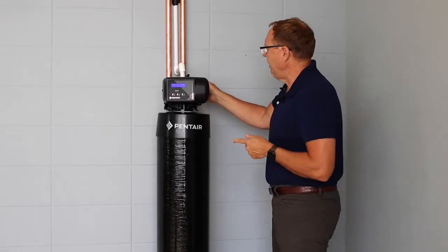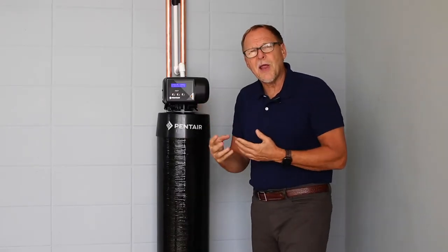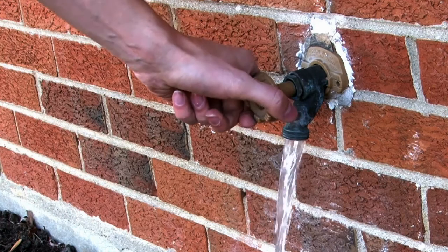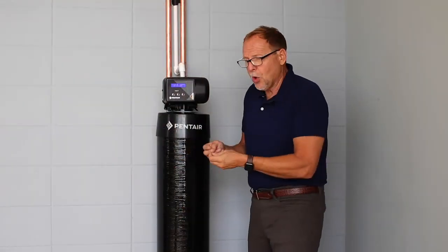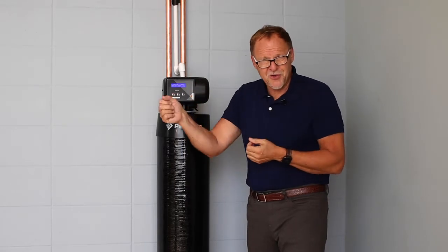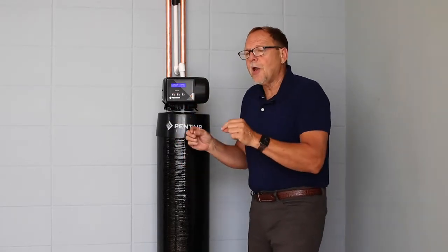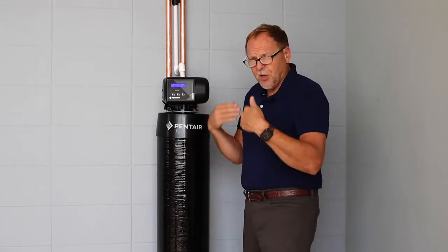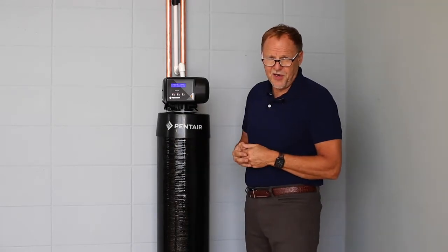It's very common on filters, especially a carbon filter, to push off some cloudy gray water. I recommend opening up a bathtub or an outside faucet that doesn't have aerators or screens, because sometimes the carbon fines or other mineral fines will go through and clog up aerators and kitchen faucets. So it's best to flush the system in an area where you don't have that, like a bathtub or an outside faucet. Once it's all clean and flushed, I can now walk the system through a cycle to test it.